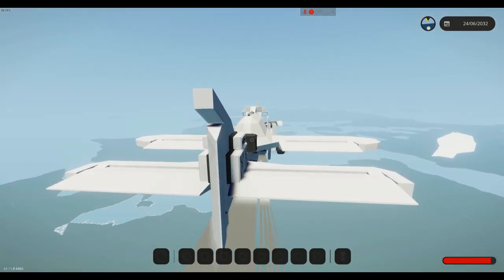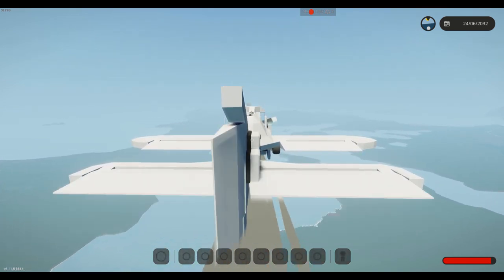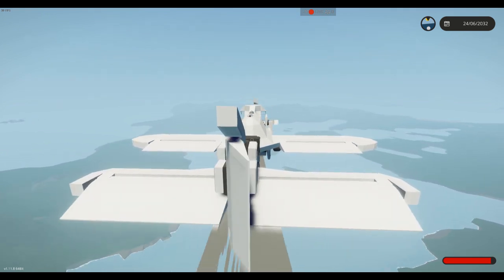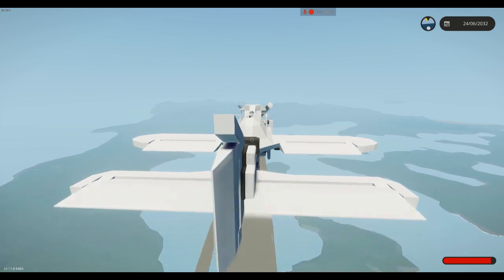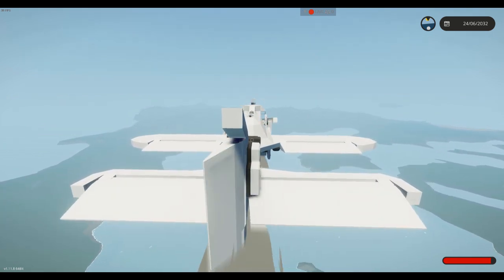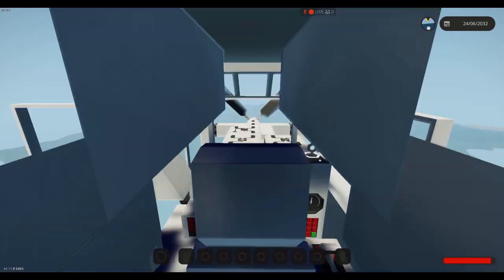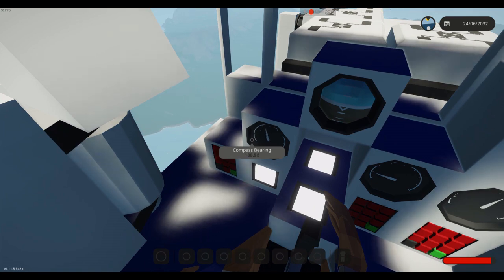We do want the compass heading to be more sensitive, because if you say put 359 in, if it overshoots, it is going to go all the way around long ways from 0 to 1 to 2 to 3, all the way 360 degrees. And so we do want a system where it does not overshoot at all.